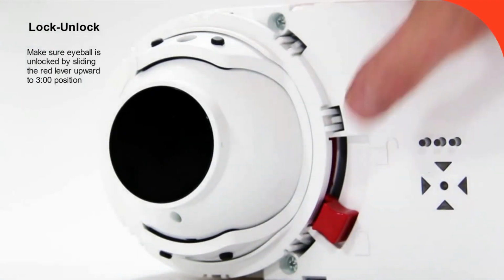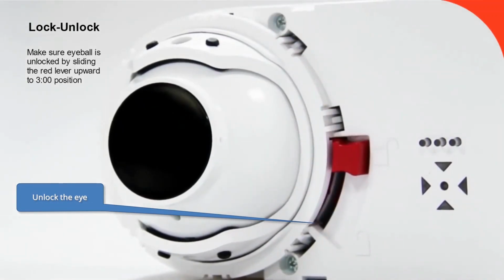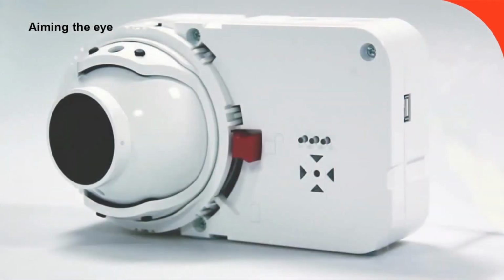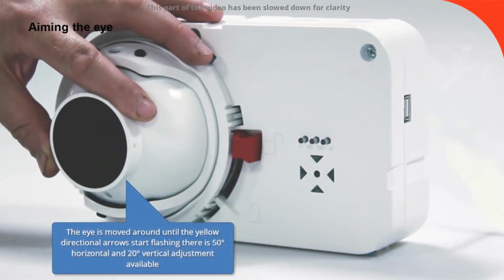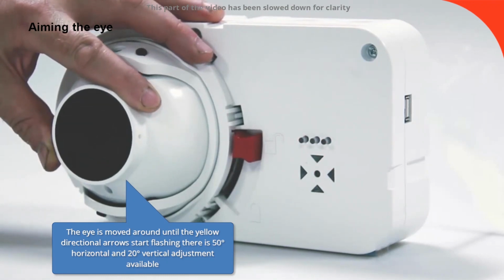Installation, lock and unlock. Once the detector is mounted and powered, you can start the alignment. To start the alignment, make sure the red lever is in the unlocked position. This allows for simple operation while working at height, with no risk of dropping a tool, causing delays in installation. The alignment procedure is child's play. Once unlocked and powered up, the eye can be roughly aimed at the reflector. The yellow arrows will quickly start to flash to indicate the required direction of movement to achieve full alignment. Once all of the arrows flash green, the lock button can be applied.